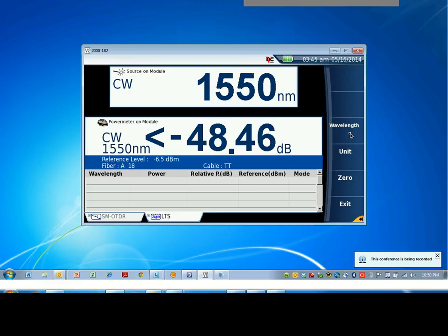Once again, wavelengths can be selected. This is a single mode OTDR, and the power meter is on the OTDR port, so only single wavelengths are available for single mode. Note the question marks, that is automatic mode. If the power meter sees a JDSU automatic wavelength, it will change from question marks to the actual wavelength. So I have wavelength 1550 selected.